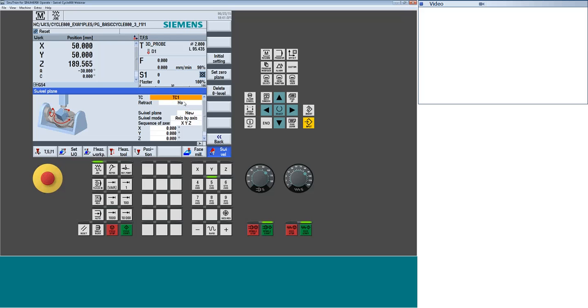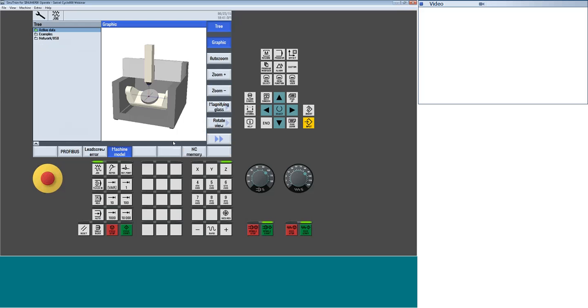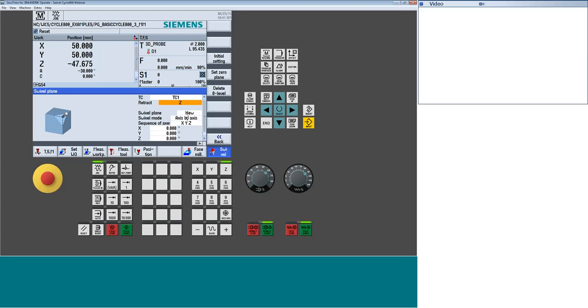The next feature that's really nice within the Swivel Cycle is the ability of managing where the spindle is. So if I wanted to return this machine back to a 0 location, but let's say for argument's sake the Z was down, so we'll take a quick look here. So the Z head is down next to the platter. So now if I had any work holding here or anything and I start to swing, I could potentially hit that spindle. Well, if I come in and tell it, hey, retract the head all the way to the top to some predefined location, then I can tell it, what do I want to do?